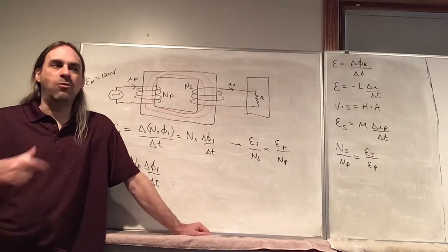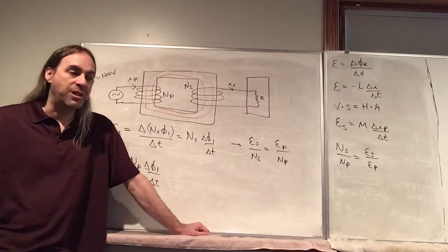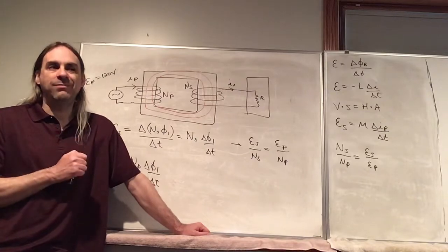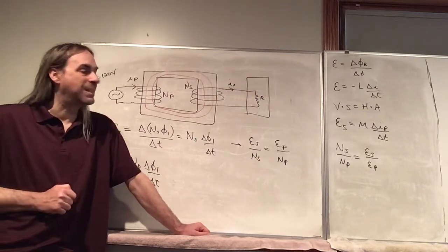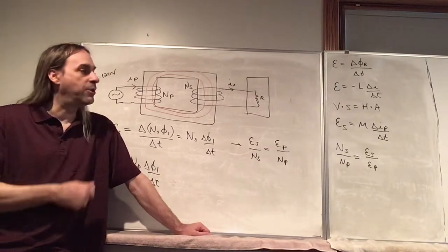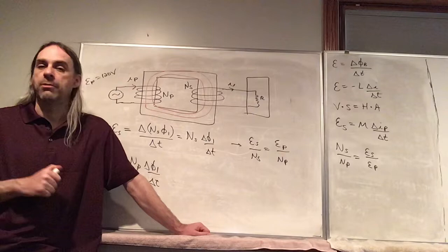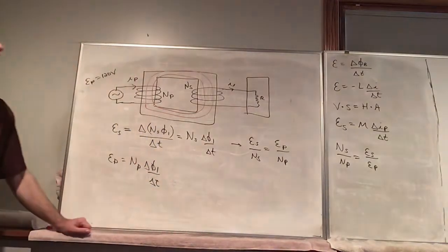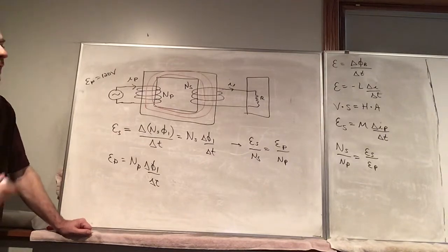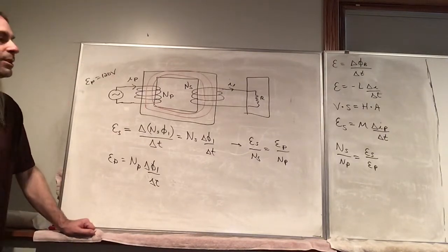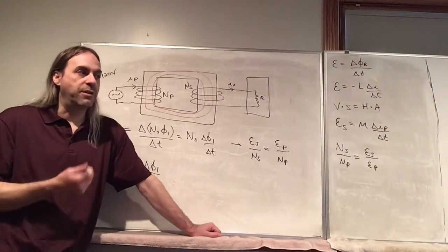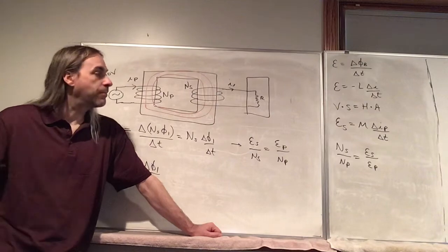But when you're transmitting a lot of energy over a large distance, that can become significant. So we use a sequence of transformers in the energy grid. The first thing they do after the power plant is use what's called a step-up transformer to increase the voltage to a very high value, like hundreds of thousands of volts. Those are the suspended cables that you see. Those are extremely high voltage, which is efficient, but also very dangerous.